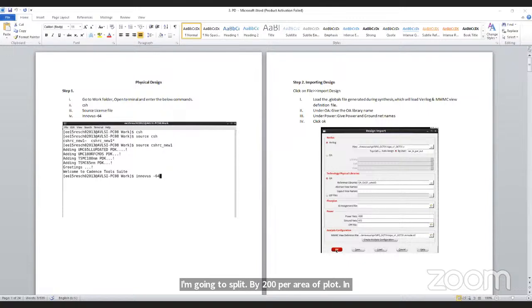And that floor plan includes my compound wall and my house room walls. Compound wall to room walls is offset area. That offset we call the IO ring area, input output pads. Apart from die area and core area, whatever we are going to declare in the floor plan.